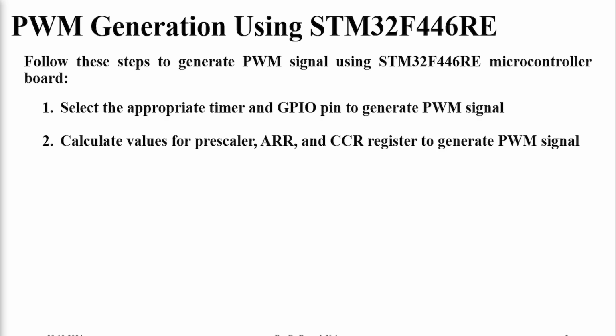Then we need to calculate the values for prescaler, auto reload register, capture compare register to generate a PWM signal.